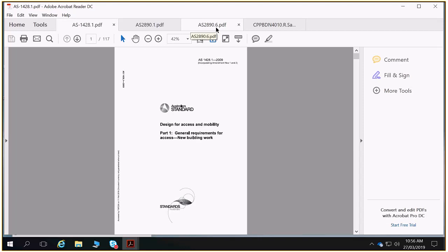The next thing you're going to have to do for thinking about your car parking is look within the council's development plan. So we've got to determine what zone it is, then see, well, you're going to have to look at the heights and so on of your building as well, but also look at what requirements there are for disabled car parking, what requirements there are for visitor parking, how many we need to have to supply as a bare minimum, and then also look at driveway widths, etc., and access to the property.